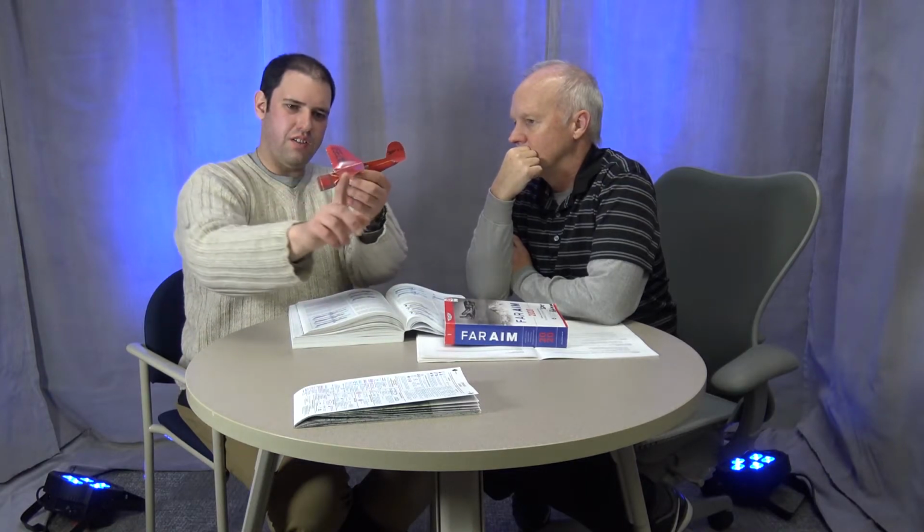Well, and the other thing that's going on there, you talked about the center of gravity. If the center of gravity is too far back, that can make the airplane unstable, because if the wing is pulling up from here and the weight is pushing down from the front, you have a sort of opposition of forces. So you have the weight pulling down and the wing pulling up, and that wants to pull the airplane's nose down. And then you have the tail counteracting that, right? This is the way we want it.